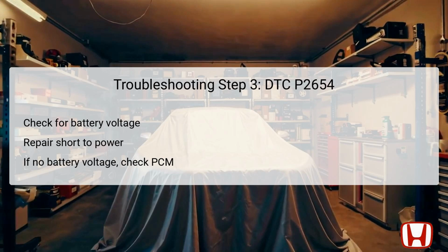Conversely, if there is no battery voltage detected, this suggests that the VTS-EX wire is in satisfactory condition, warranting further investigation. At this point, reference any authorized service information associated with DTCs or symptoms observed. It may also be prudent to substitute a known good PCM to assess whether it resolves the issue, making it easier to determine if the original PCM was faulty.